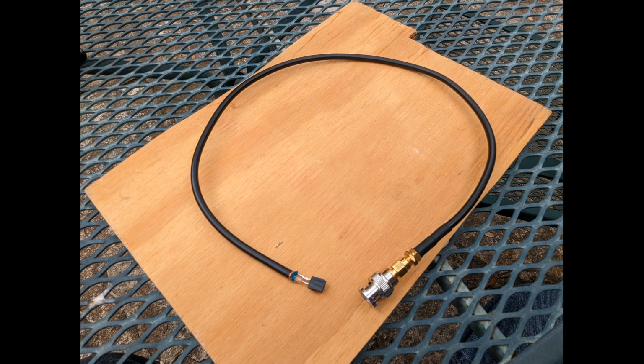So the Siglent oscilloscope is set for a 1x channel. And that's important for small signals. If you used a 10x probe, the already small signal would be divided by 10 in amplitude and then would just have to be amplified by the oscilloscope, and that adds noise. So it's better to use 1x, provided the signal frequencies are low enough that you can live with the bandwidth limitations of 1x probing. The Wien bridge is connected to the Siglent oscilloscope just using a normal probe with its flying ground lead. Remember, the frequencies are small here, and that channel is also set to 1x.